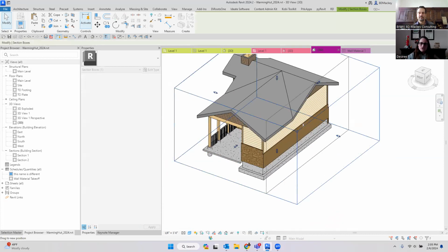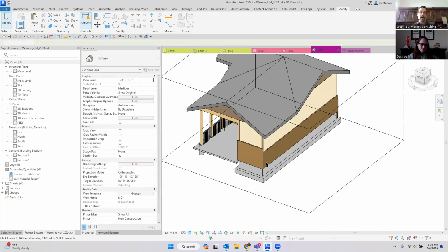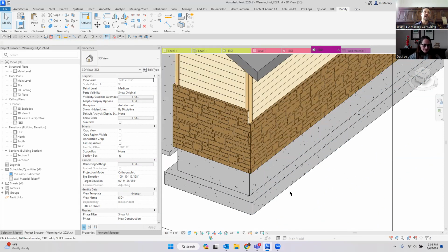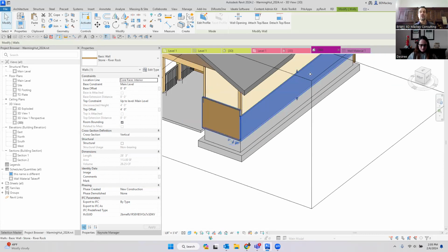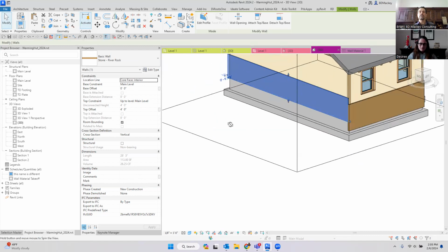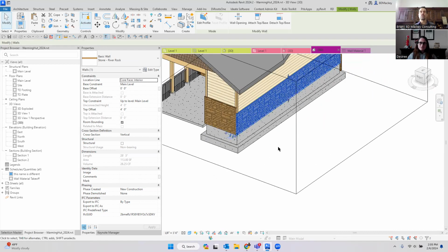And then Marta wants to know why didn't you stack walls? I am not a big stacked wall fan. Matter of fact, I completely despise stacked walls. Part of the reason I wouldn't use stacked walls is in an exact scenario like this. If I had used a stacked wall and I wanted this one to be 4 feet tall, but this one to be 5 feet tall, and this one to be 6 feet tall, that is 3 individual stacked walls. So I've got to have one where the base wall is 3 feet, the one where the base wall is 4 feet, and you're constantly going through and creating duplicates for the different heights.